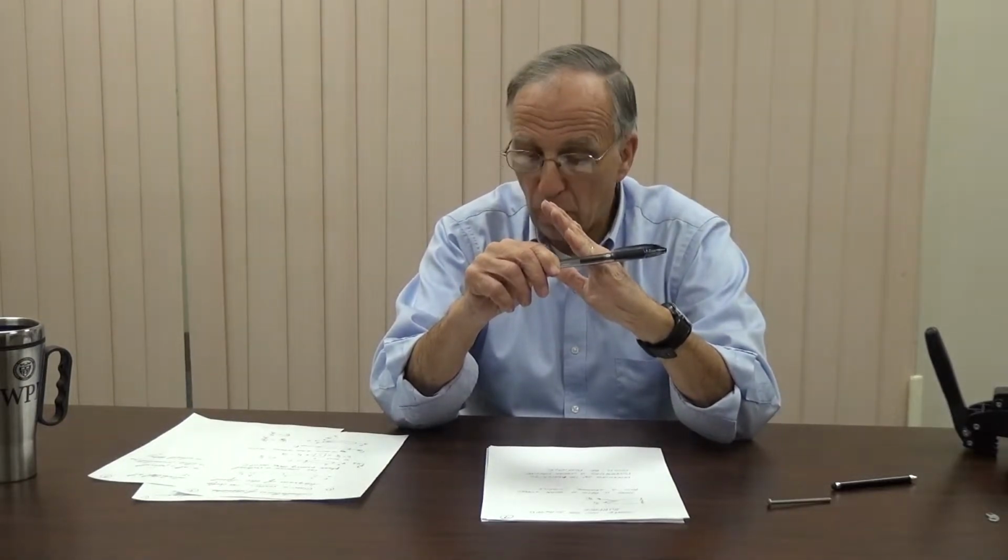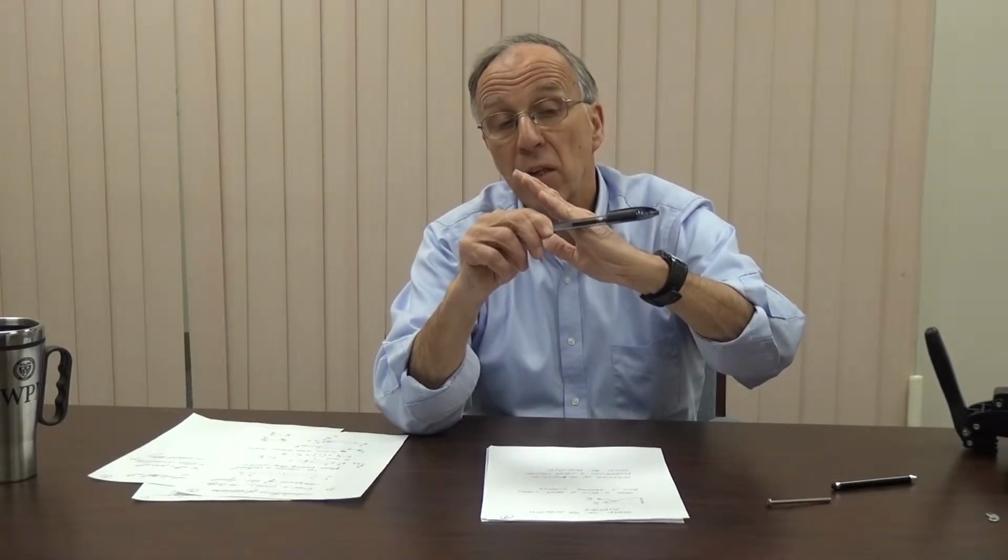So, depending on how I cut the object, depending on the plane that's passing through the very same point, I can have only normal stresses for a plane like this, and I can have normal and shear stresses acting on a plane like that. And we can carry this further into the analysis of materials by looking at simple ways in which materials fail.